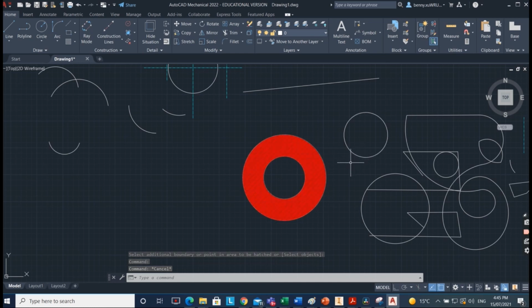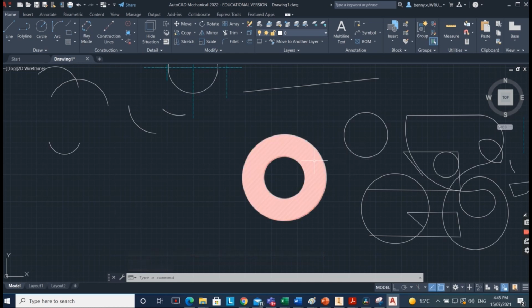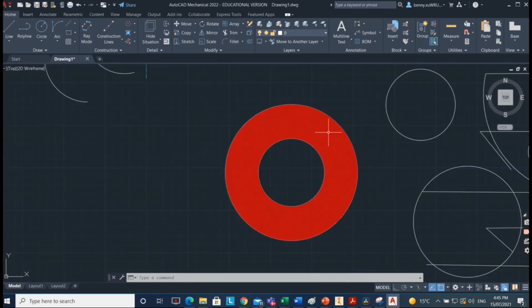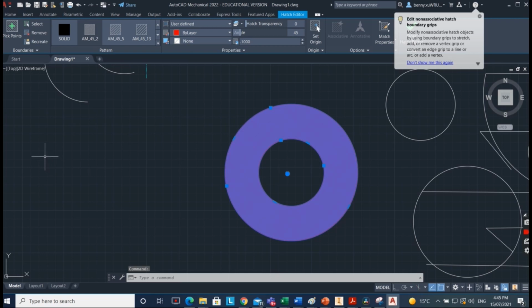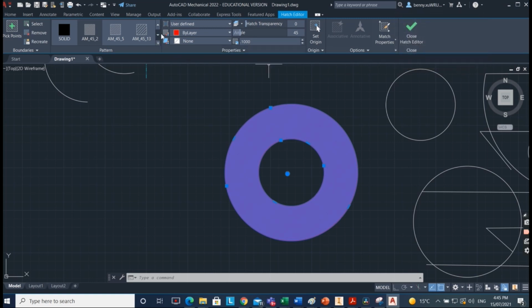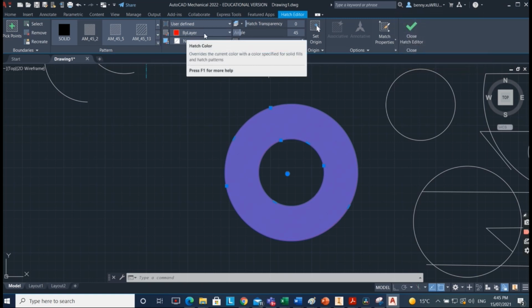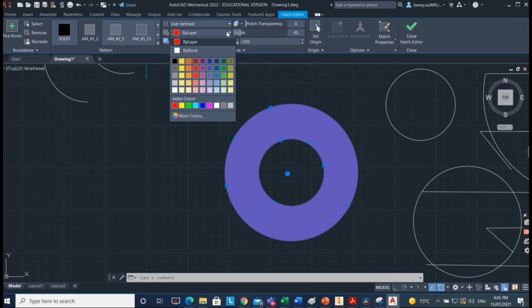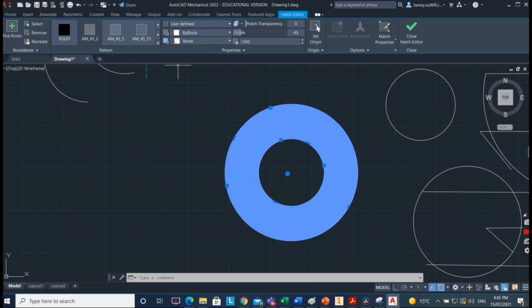And originally, maybe the setup is in orange color, lines too close. So therefore, you need to click once, left hand click once in there to change all the details. For example, this is by layer. I'm going to change it to by block. This block is X and Y. And then color for fill, I don't need to fill in the color.